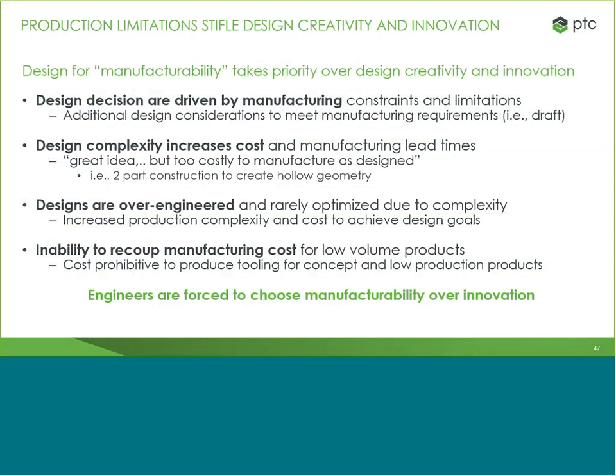So a lot of the decisions you need to make are actually driven by the manufacturing constraints and limitations. You also have to create additional geometry sometimes because you need it to support the manufacturing of the product. An example would be adding draft to a molded part. But the reality is, as an engineer, I don't have the freedom. I have to make the part, right?